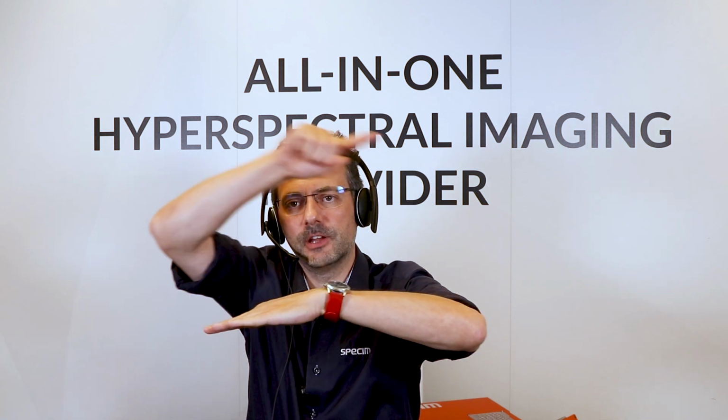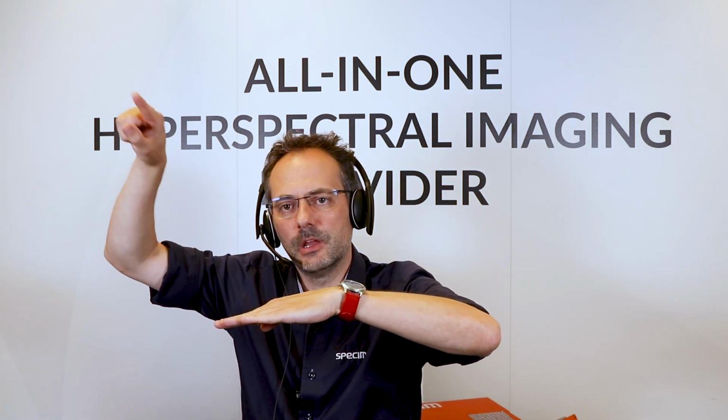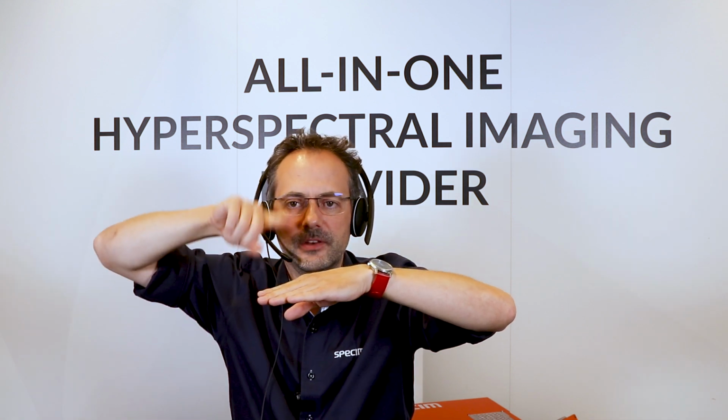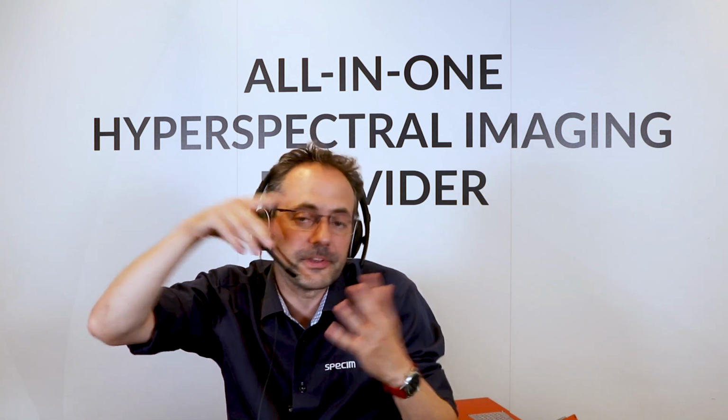But the one we were showing in the PowerPoint was based on interferences. You imagine you have the thin film like this, the light source here, and you are looking in a specular fashion. Depending on the film thickness, you can have interferences with a shorter or longer pattern between the interferences. With the FX10, we recommend a thickness between 1.5 and about 30 micrometers. You can also use the FX17 to do that, but for thicker films.